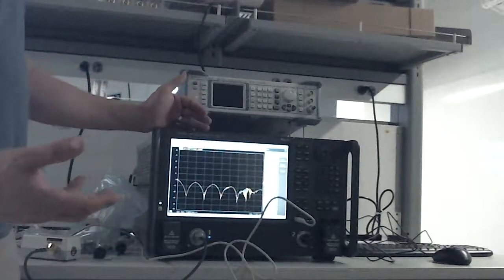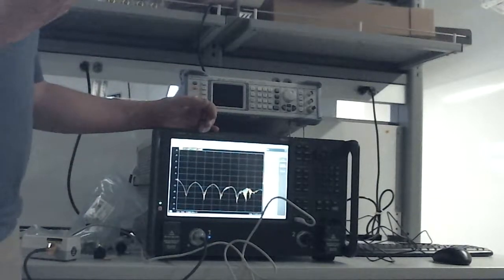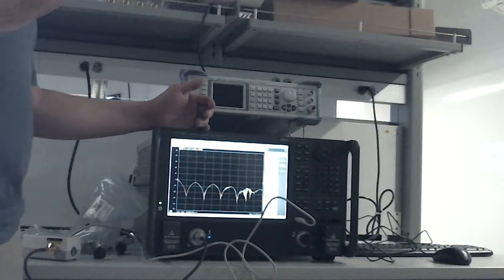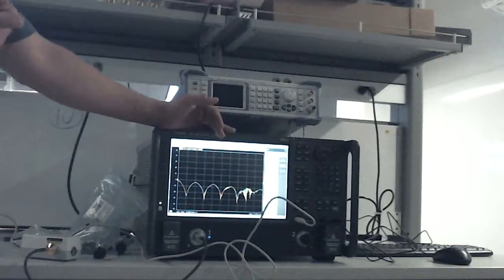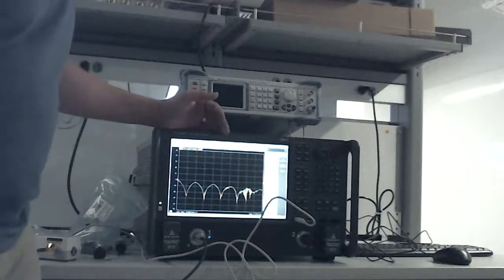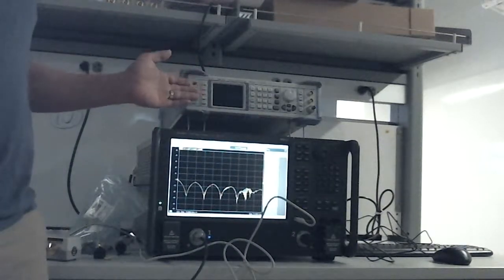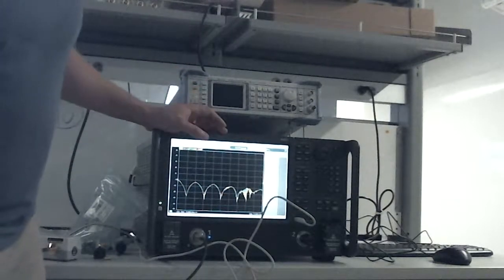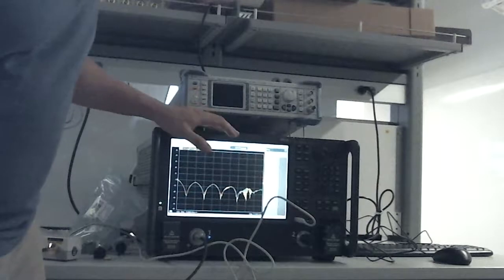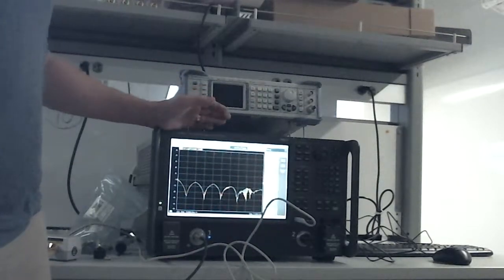In terms of the measurement, what you really want to think about are sort of, I guess, three things. First of all, what's the frequency range that you're going to measure? And this is probably going to be the most critical thing for you guys. So, you just hit frequency here. There's a start-stop. There's a center span. Whatever method you guys prefer to specify. There's also, for the sweep, you can also set the number of points.